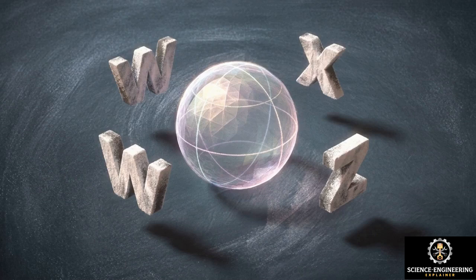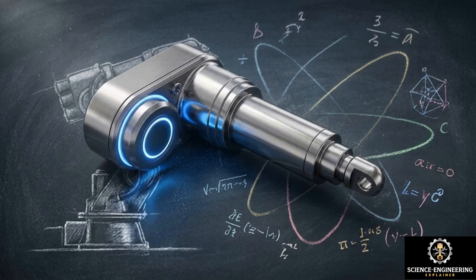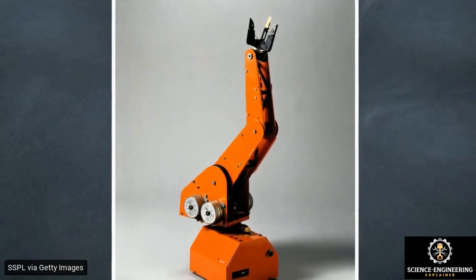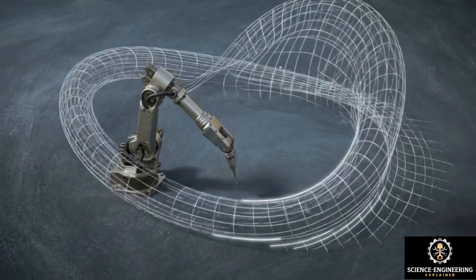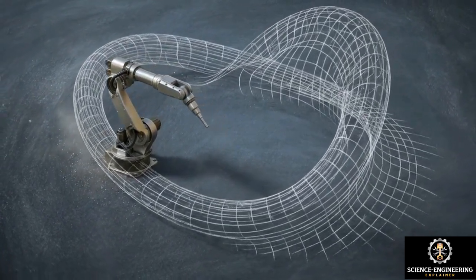We represent orientations strictly through Unit Quaternions. We calculate precise, uniform paths using SLERP and SQUAD, and we drive the mechanical hardware using pseudo-inverse Jacobian control. Calculating flawless spatial motion requires more than linear approximations. It requires abandoning the flat space geometry of human intuition and engineering directly within the topological curvature of the SO3 manifold.